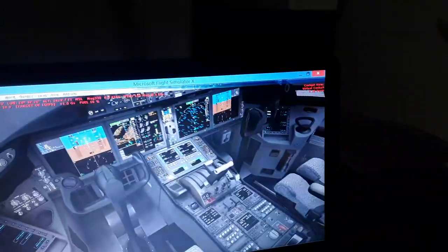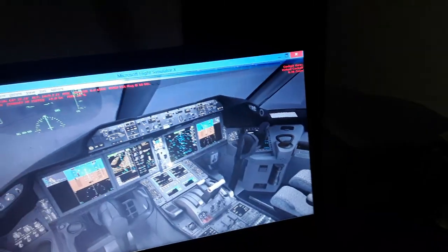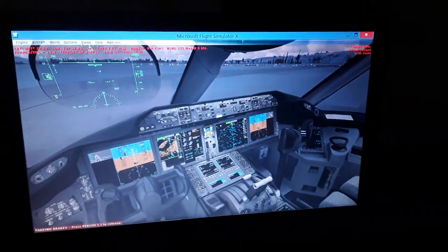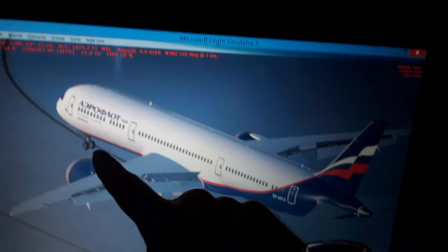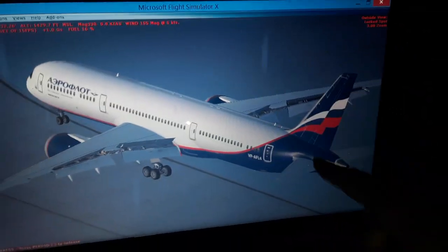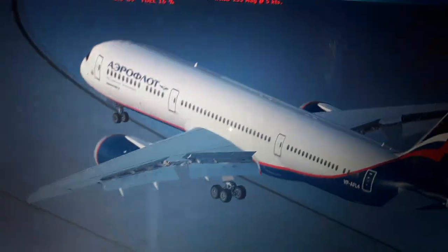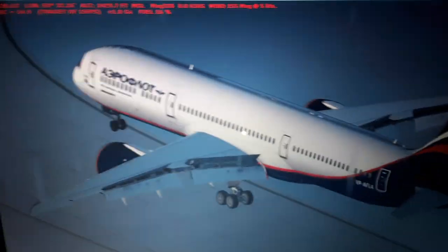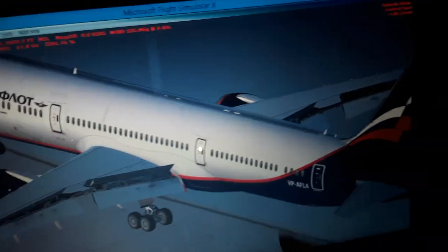We also have the tiller, left and right tiller over here. Both rudder pedals move together, they are interconnected. The tiller is only for the nozzle. From 0 knots up to 45 knots, or 72 kilometers an hour, the nozzle will be deflected automatically by the computer, from 0 to 76 degrees for left and right turns.